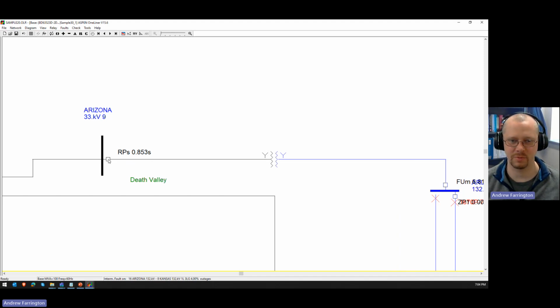The recloser is probably a three-phase device, so all three phases would open and you're going to have that customer power quality problem. But I should have also said that fuses don't reclose. And so if this were a temporary fault, the recloser gives you those opportunities to restore power to everybody without having a prolonged outage. If the squirrel got burned off and he's gone, well, now we can restore power to everybody. So fuses don't reclose. That's another problem.